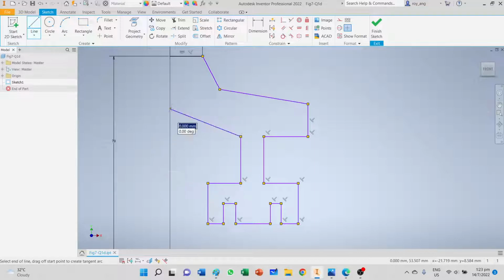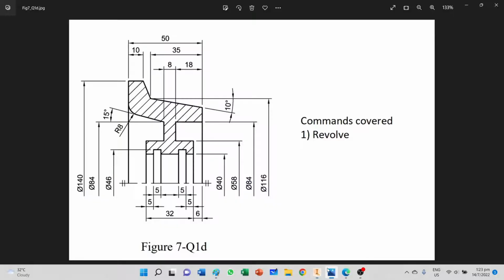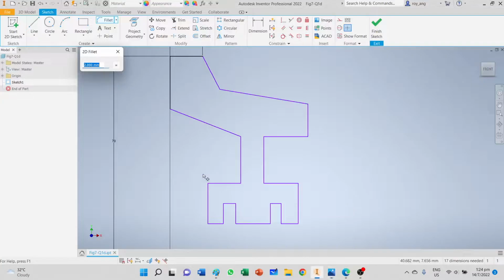Okay, so I'm going to just click here. Oops, it created a radius for me, and I'm closing that. Okay, I can add in the fillet right now, and the fillet at that corner, according to the diagram, is R8. Okay, it's R8. So I'll just put 8, and I select one edge, I select the other edge, and I have an R8 over here.